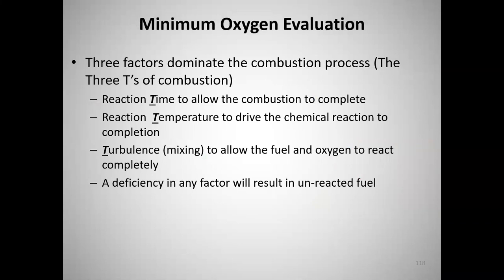Babcock and Wilcox a long time ago said that for proper combustion, three factors dominate the combustion process. They call these the 3 T's of combustion. And you've got to get these right to have good combustion. You've got to have time, temperature, and turbulence. Time at temperature for the oxidation reaction to complete. It takes time. It's not instantaneous. Reaction temperature, you've got to be above that combustion threshold.